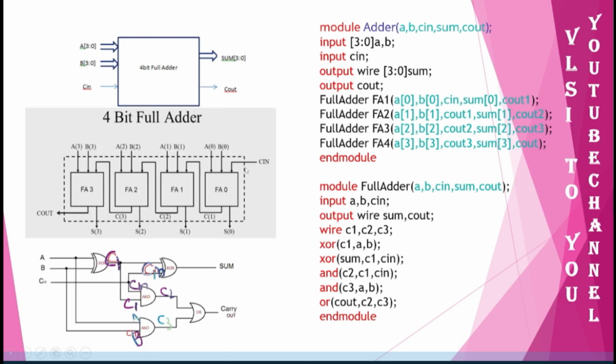Okay, now what I am going to do is write the code for one full adder. Now if you see here, this is my one full adder code. Okay, A, B, C in, sum, C out. So based on the structure I am writing the code. Here, this is my 4-bit full adder. For this I am having 3 inputs, A, B, C in, and A and B are 4-bit wide, since it is a 4-bit full adder. And since A, B are 4-bit wide, the sum will be 4-bit wide and C out is 1 bit.